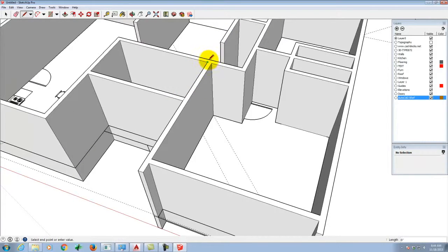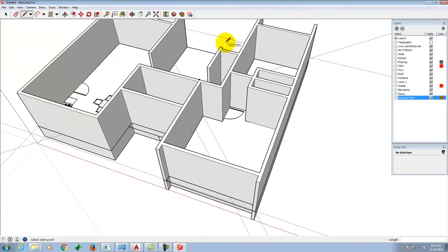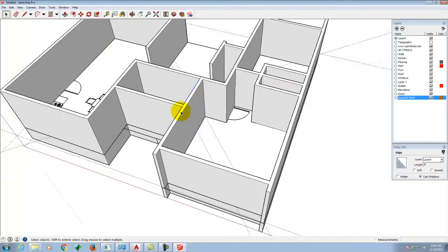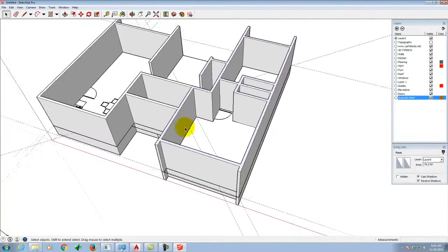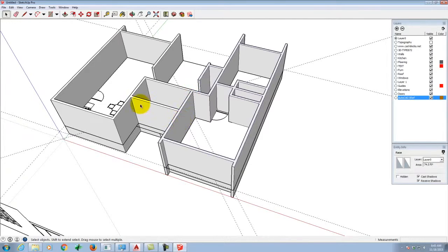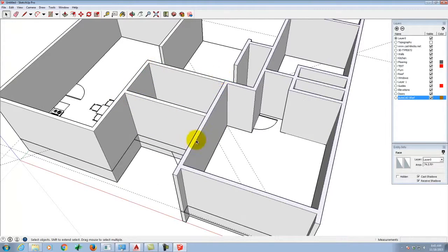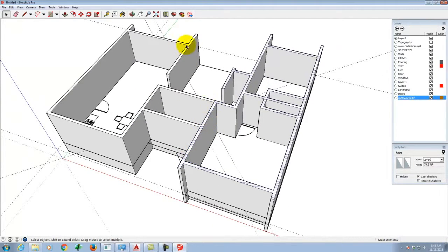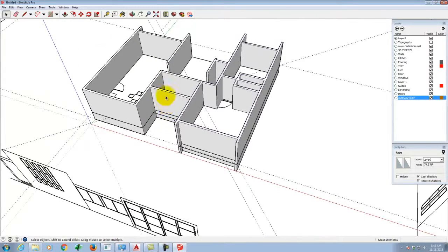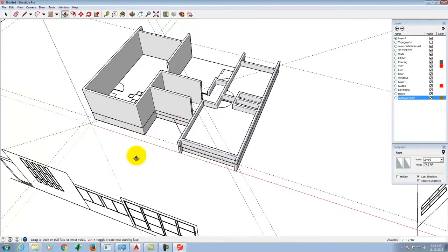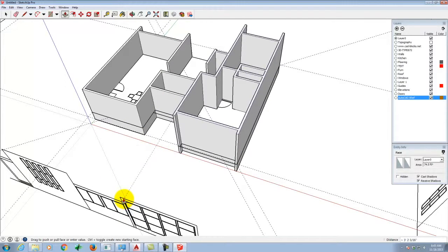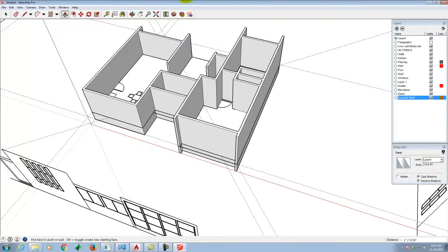We'll divide it there. And that one's fine. And I'm going to select this piece right here. And you see that when I divided that, this part of the surface isn't selected anymore. It's only this part. And I can then use the push-pull tool again. And we can pull this part up a little bit taller. And so we're going to pull it till it snaps to that point.